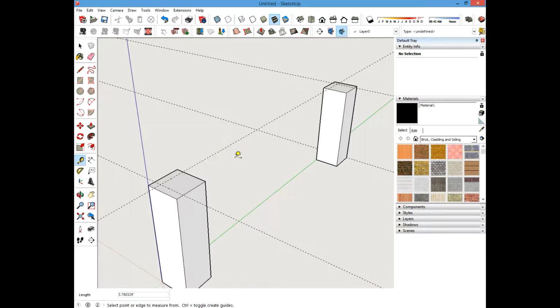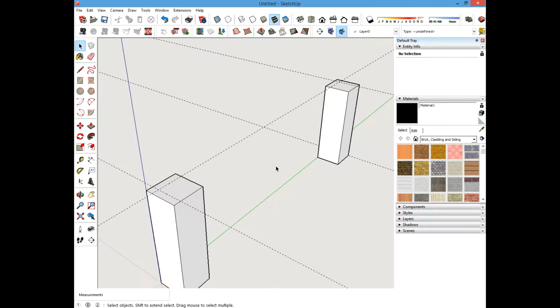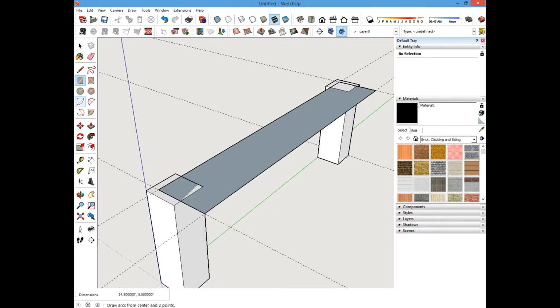I'm going to take this line and create another snap line that will define our first board. So again, if you were to Google actual wood sizes, one of the first entries that comes up is a handy table that will tell you the actual wood dimensions. So if we're going to use, let's say, a 1x6 board here, it'll tell you that it actually measures 0.75 inches by 5.5 inches. So let's come this way, 5.5 inches. So I'll just type 5.5, enter. And this is going to be our first board here.